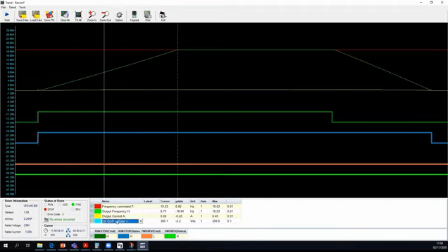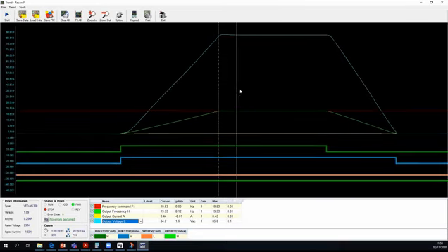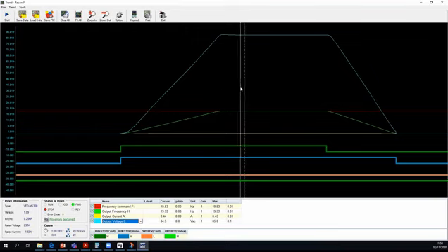And you can also monitor different parameters here. And VFDsoft actually monitors all of these parameters at one time. So if you click on output voltage, you can also see the drive increasing the output voltage up to the corresponding VF curve. Because the drive is running in open loop, it just follows a linear VF curve. So you can see the output voltage increasing proportionally with the frequency up to a maximum of 84 volts.